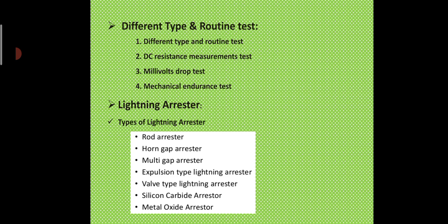Different types of routine tests need equipment such as an ultraviolet recorder or UV recorder, oscilloscope, and potentiometer. No load tests are carried out on the following conditions: for solenoid operated, closed solenoid energized at both 105% and 85% rated supply of closing coil.